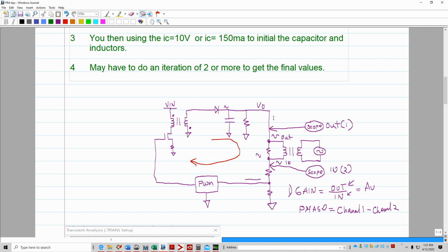This would be a very simplified flyback. You have your transformer, your output filter, and your divider resistor here. Then this is your sample feedback, PWM, and so forth. So this is a loop. Typically on an actual power supply that sits on your bench, you'll add a 10 ohm or maybe a 100 ohm resistor. That's your injection site, and you'll have two test points, an out and an in, and then we use an injection transformer.